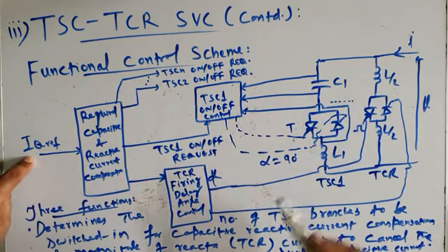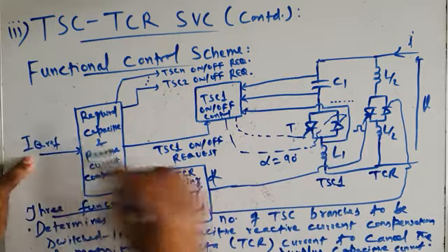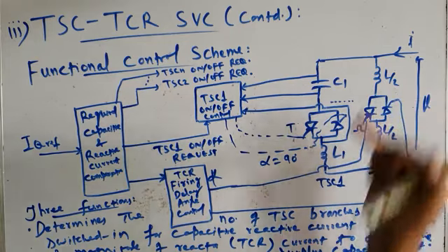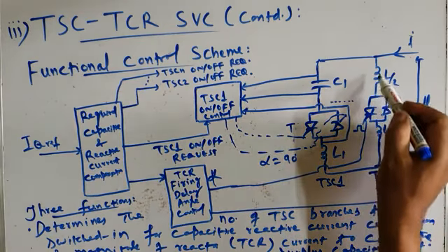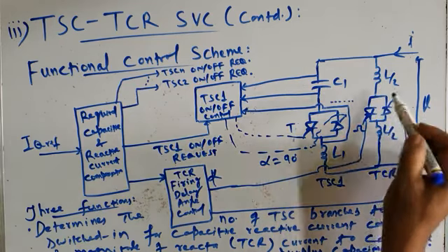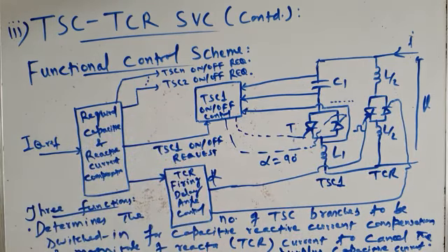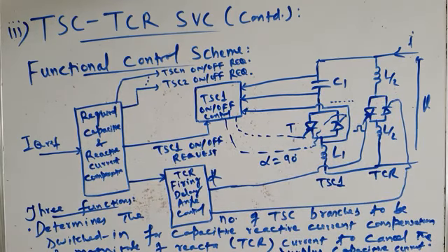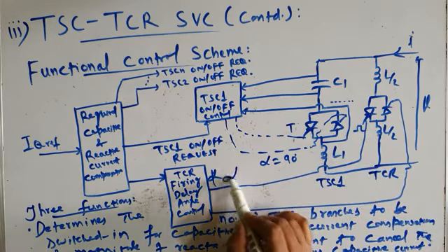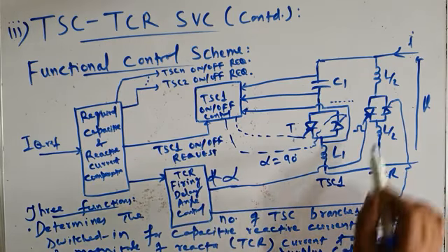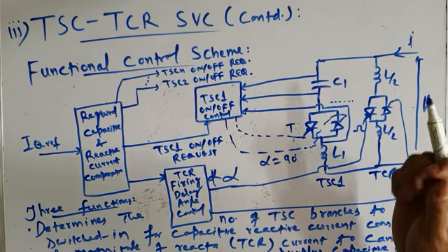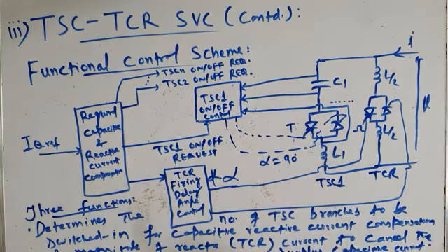So the surplus reactive current, which is IQ ref minus injected current, has to be absorbed or drawn by the thyristor controlled reactor. The magnitude of inductive reactive current will also be calculated by this block, and depending upon how much reactive power this TCR has to absorb in terms of the inductive current, it adjusts the delay angle alpha of TCR and issues the firing pulses to the switches of this TCR. TCR turns on, and it compensates for, or cancels, the surplus capacitive current.